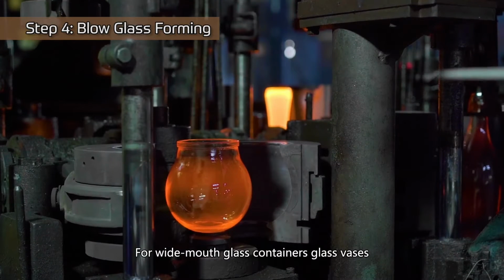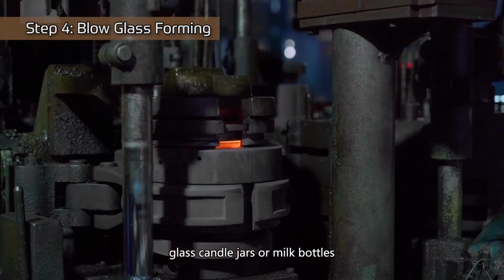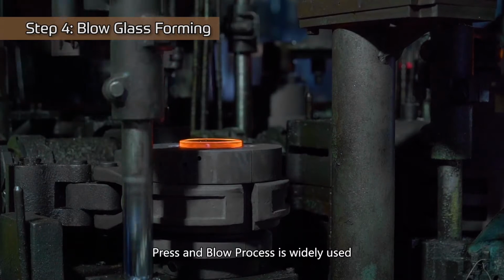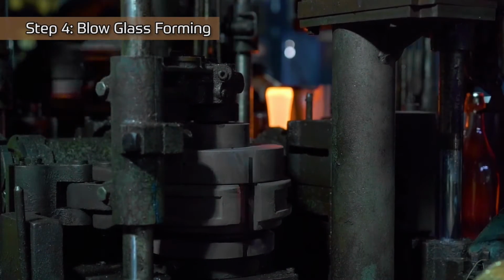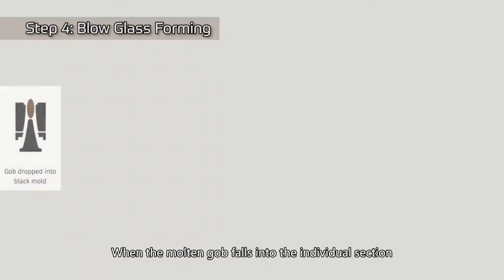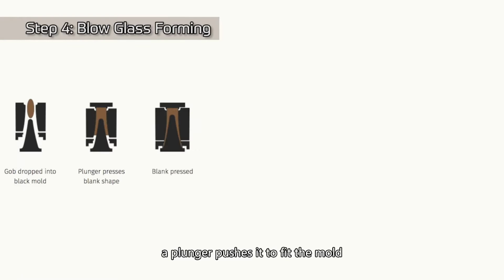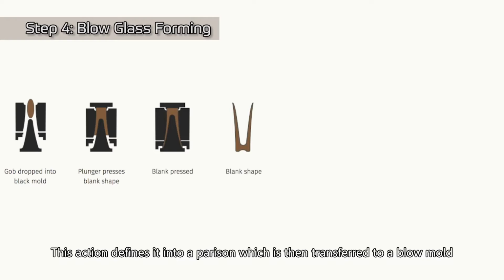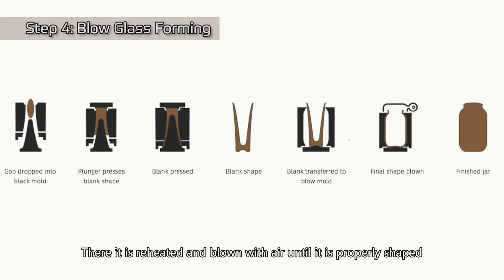For wide-mouth glass containers, glass vases, glass candle jars, or milk bottles, the press and blow process is widely used. When the molten gob falls into the individual section, a plunger pushes it to fit the mold. This action defines it into a parison, which is then transferred to a blow mold. There, it is reheated and blown with air until it is properly shaped.